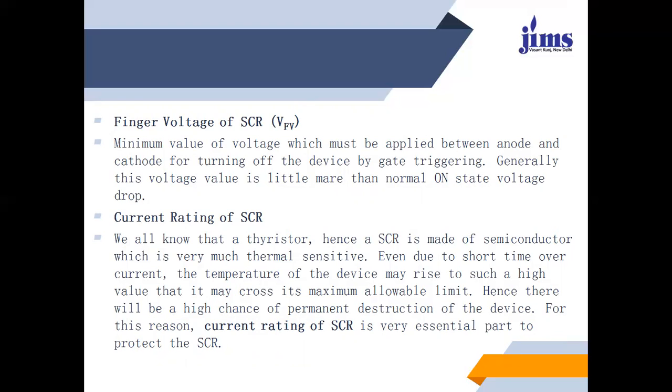The next parameter is the current rating of the SCR. We all know that a thyristor, or SCR, is made of semiconductor which is very thermally sensitive in nature. Even due to a short-time overcurrent, the temperature of the device may rise to such a value that it may cross its maximum allowable limit.